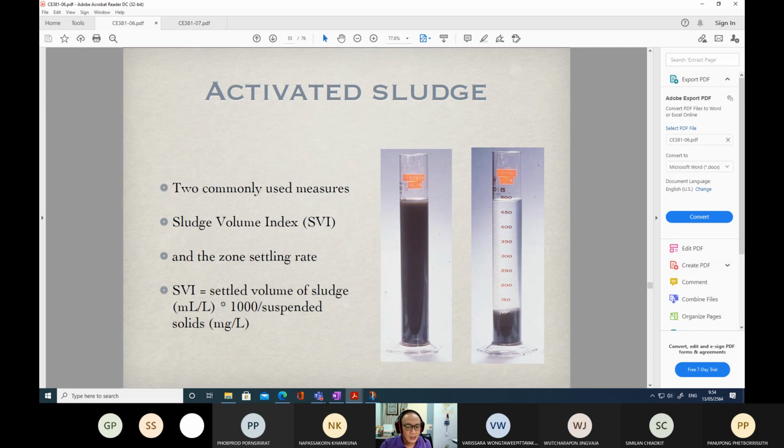Soon after, we switch off the aeration machine, or we transfer this liquid into the sedimentation tank. We can observe this separation. All the suspended solids will accumulate at the bottom of the chambers, and we only decant the clear water to the natural receiving stream.